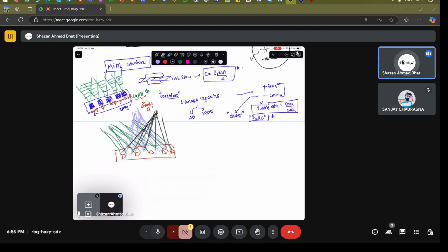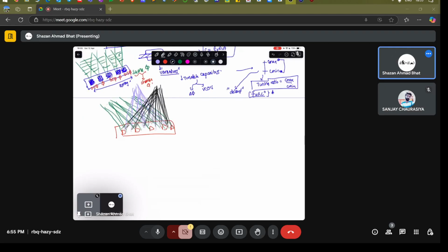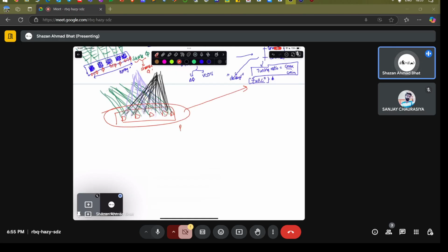It's a beautiful concept which is used in radar. Military systems use it most often. The drones use it. The jamming antennas use it. All of those systems use it, and you don't have to move the physical system, you just have to change the phases. And how does this happen? This happens because if you change the phase of microwaves coming out of it, you're destructively and constructively creating interference patterns.